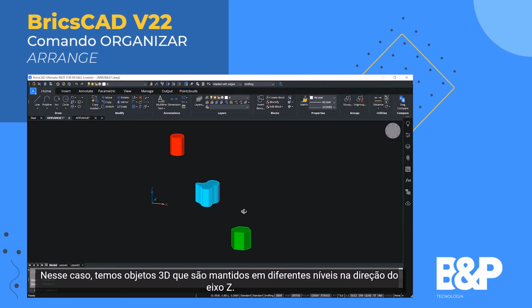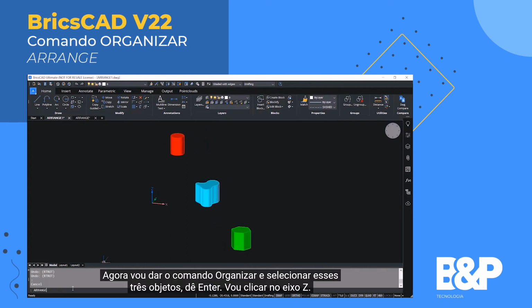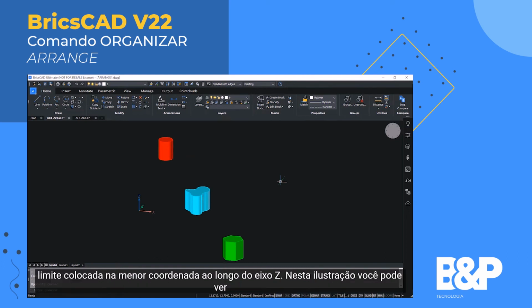In this case, we have 3D objects which are kept in different levels in the z-axis direction. Now I'll give arrange command and select these 3 objects, give enter. I'll click on z-axis. The lower align aligns the lower bound of each entity with the lower bound of the selection bounding box in the z-axis direction. The lower bound is defined by the face of the bounding box placed at the smallest coordinate along the z-axis.